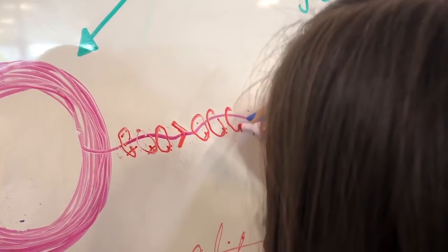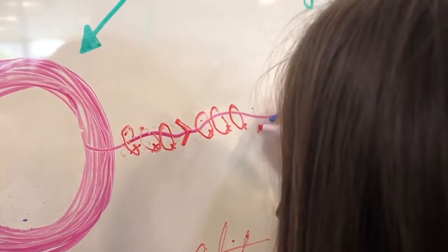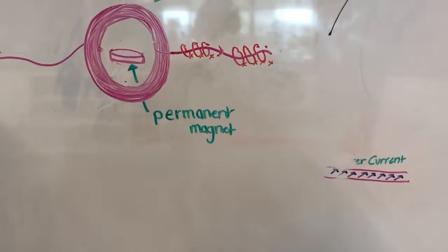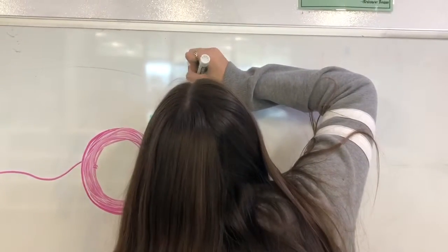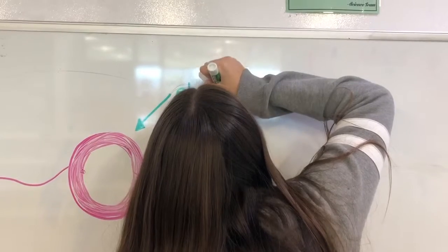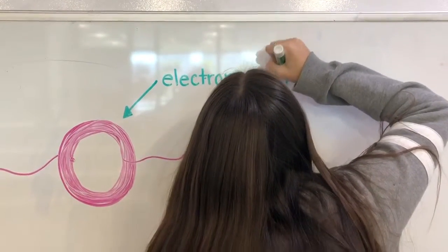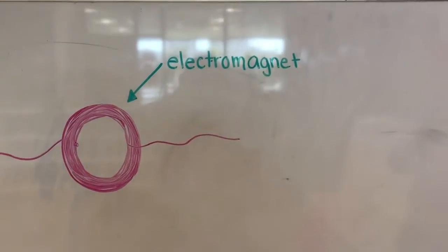The back and forth movement of the wire presses and pulls on the diaphragm of the speaker, which leads to vibrations in the voice coil. This creates a wave of compressions and rarefactions by which sound is propagated in an elastic medium such as air. Put in simpler terms, the now sound waves then exit the diaphragm.